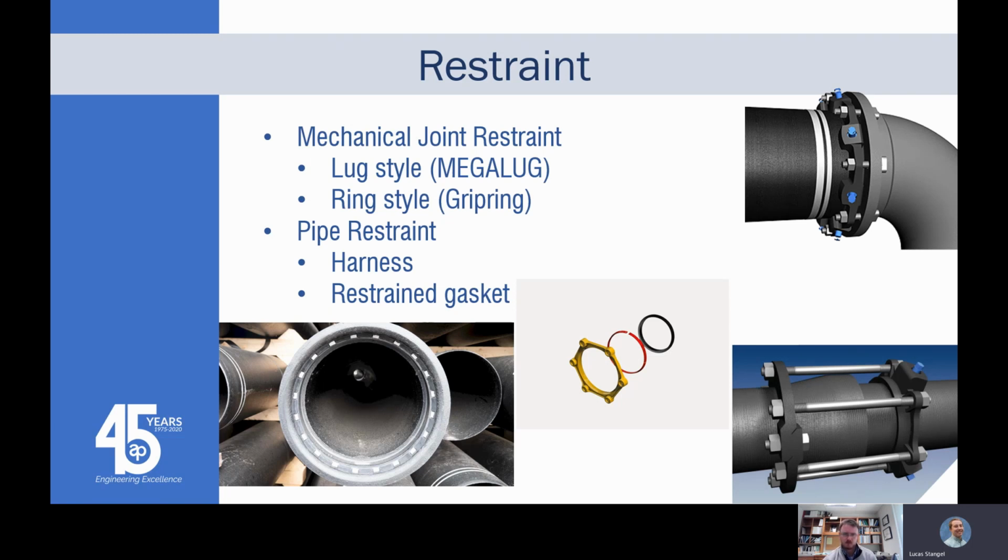You do want to be careful with the restraint when you talk about PVC. There are special products made for PVC pipe. You don't want to necessarily use the ductile iron mega lug on a piece of PVC pipe. It's going to cause some damage. Anything to add? No, I think that's great.